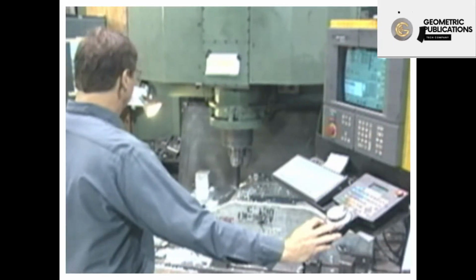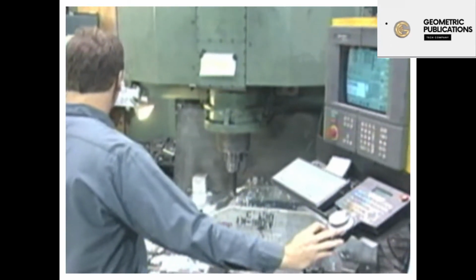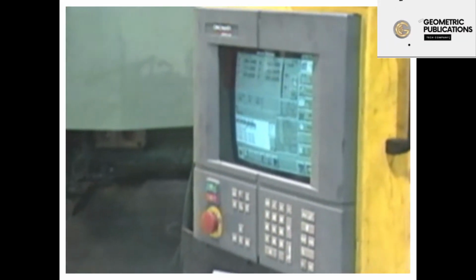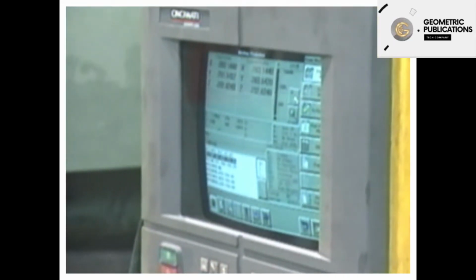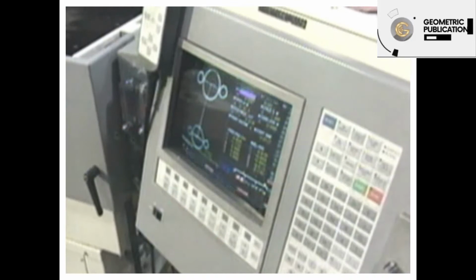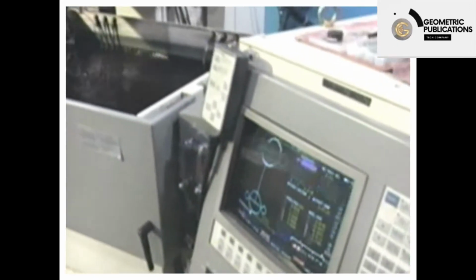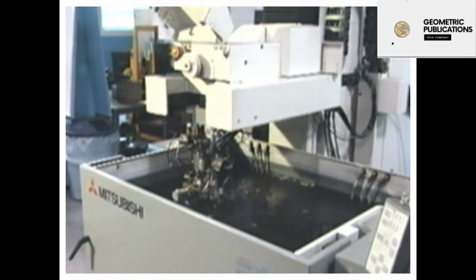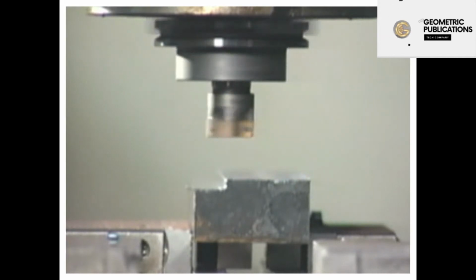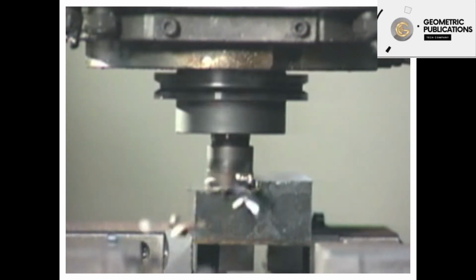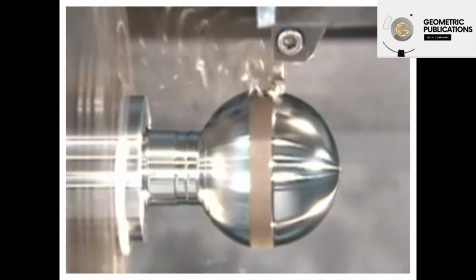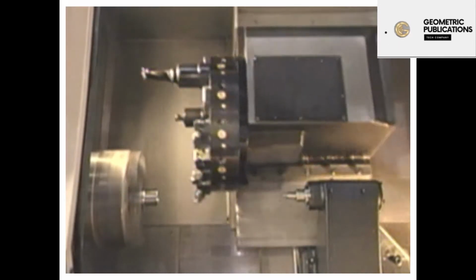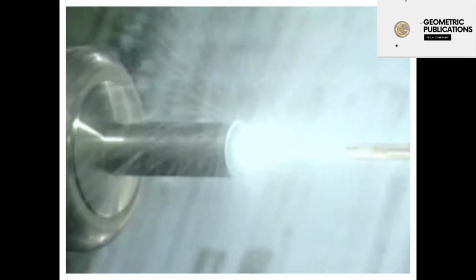Computer numerical control, or CNC, built upon the standard numerical control production capabilities by incorporating an integral computer processor to govern the machine controls. Programmed instructions, or data, in the form of a part program, is translated by the machine control into output signals that control machine functions, such as spindle rotation, cutting tool movement, workpiece movement, tool changing, and cutting fluid control.